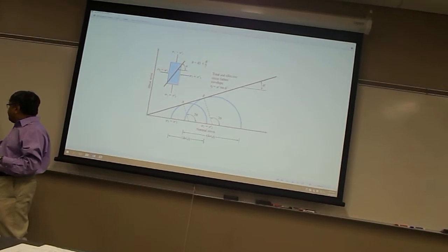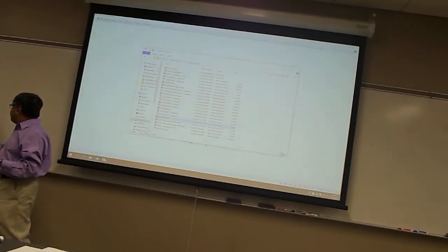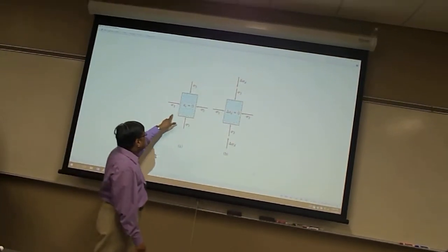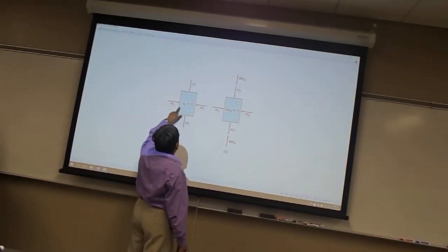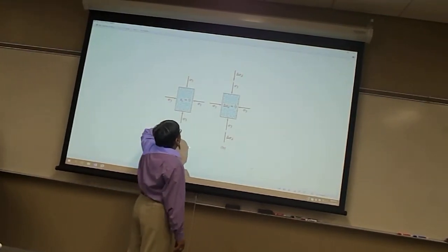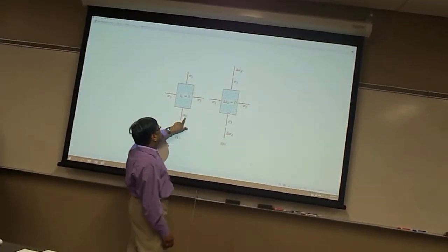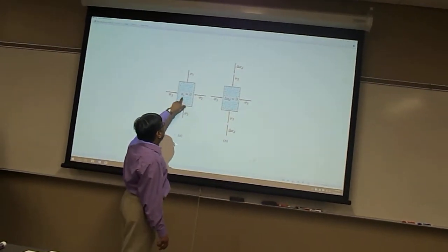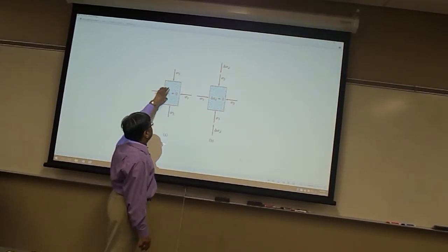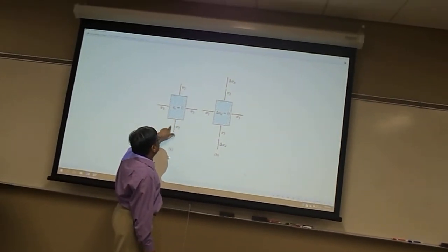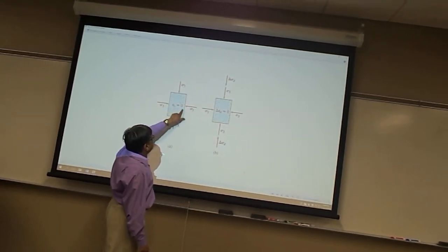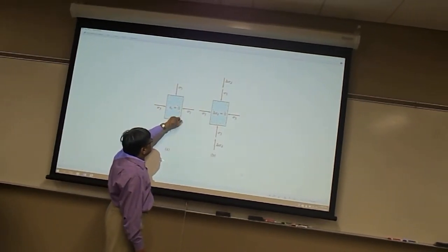That's also explained in this figure. When we do this consolidated drained test, in the consolidation stage, we apply sigma 3 also equals sigma 1. That's why instead of writing sigma 1, sigma 3 is written here. We allow the soil sample to consolidate. That means we allow drainage in both the vertical directions, top and bottom, not allowing the pore water pressure to develop.